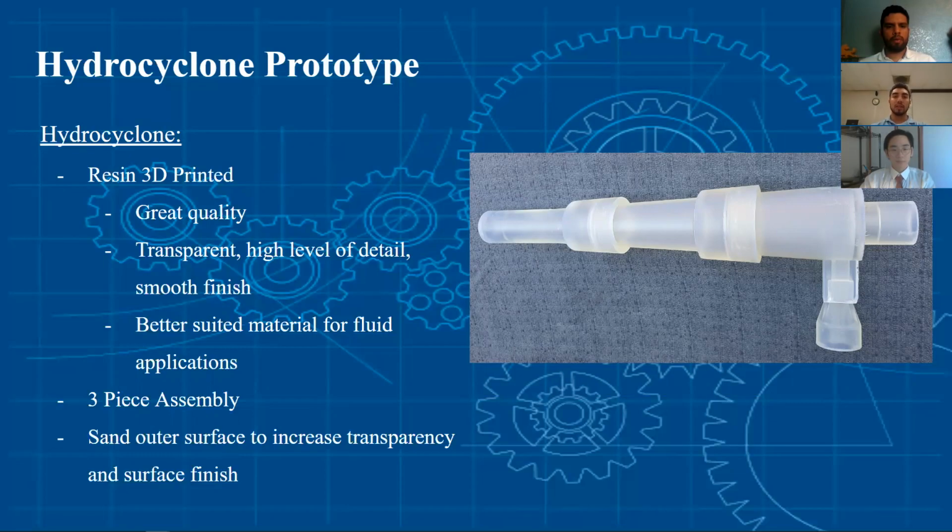As previously stated by Patrick, the hydrocyclone's dimensions were governed by Young's recommended design criteria, which resulted in producing the highest efficiency from all the experiments we studied. Based on Young's design criteria, our original hydrocyclone dimensions were beyond the 3D printer's printing range and resulted in redesigning the original one-piece design into a 3-piece assembly.